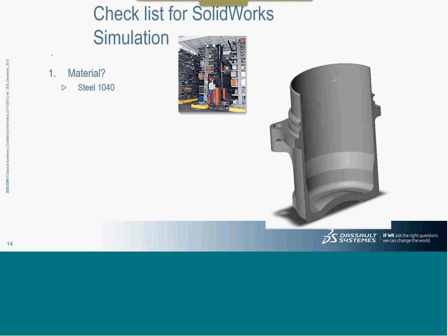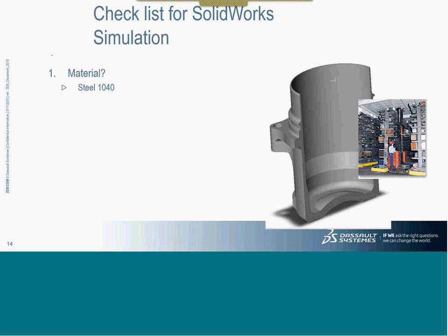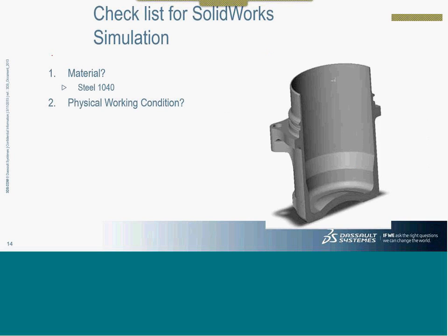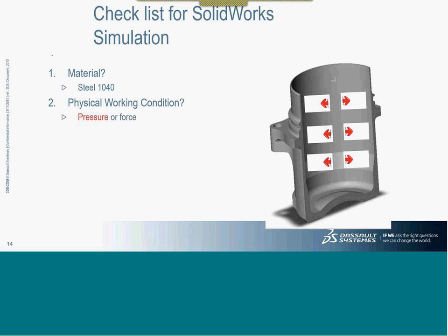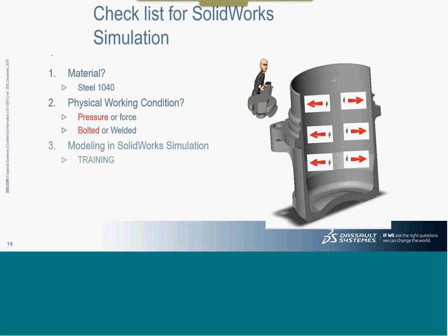We have understood the process and a few basics of simulation. Before you start the analysis, in the pre-processing part, we do a few different things. We need to understand what material has to be used, and ensure it before the analysis. Then the physical working conditions. These could be the forces being applied, or temperatures, or anything else. We need to have a good, detailed understanding of these three things. These forces could be pressures, or welded loads. All of those need to be understood.